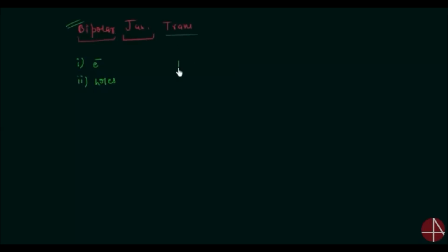The name transistor is made of two words. The first word is transfer. And the second word is resistor. We have two junctions in transistor, J1 and J2. If junction J1 is forward biased, it will offer very low resistance. If junction J2 is reverse biased, it will offer high resistance. Weak signal is introduced to the low resistance and output is taken from the high resistance. Thus BJT transfers a signal from low to high resistance.